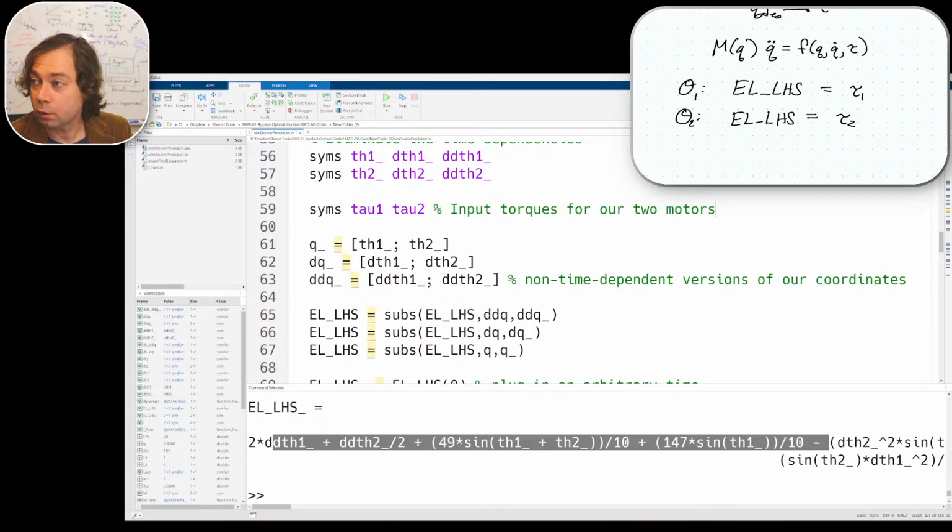Okay. Now, the only thing that we talked about in previous lectures is that, don't forget, Newton's third law still exists. Even though we're doing Lagrangian mechanics, it still describes actual real life forces and actual real life control laws, okay? So that means there's an equal and opposite torque on our first degree of freedom. Why? Because that motor would be mounted to my upper arm and then connected to my lower arm. So it's right at my elbow. So any torque I apply to my elbow, I get equal and opposite torque to my upper arm, okay?